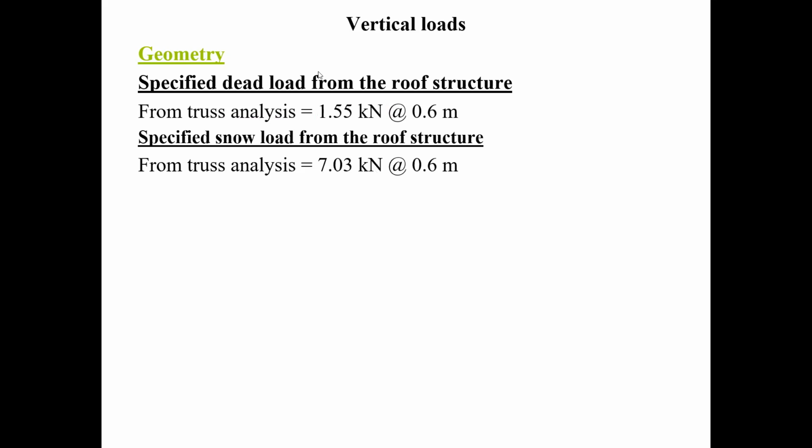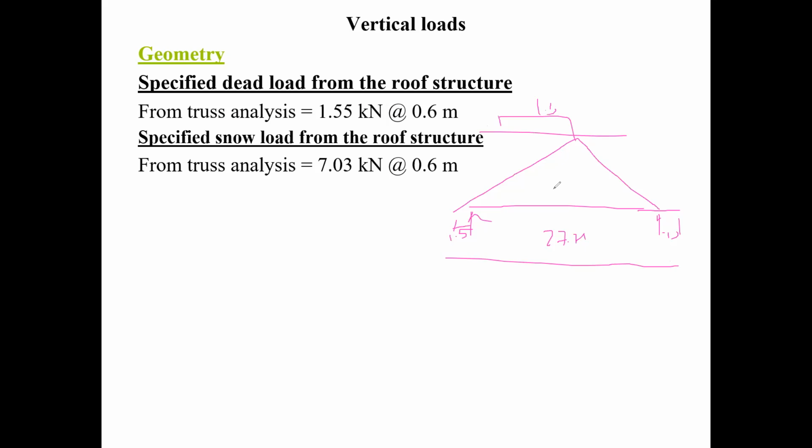Now, if you want to take your time, this is your truss here, and you know that this was 1.5 feet, this was 1.5 feet, and this was 27.75 feet. Convert this all into meters and take that. We had a snow load here of, I think, 1 point something, and if you do it, you're going to get exactly the same value. So it's up to you.